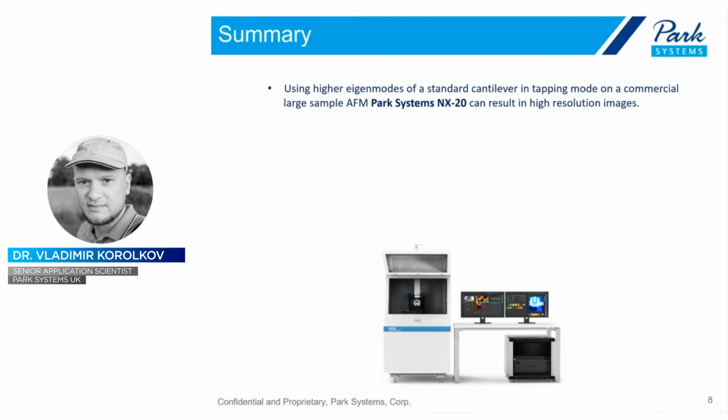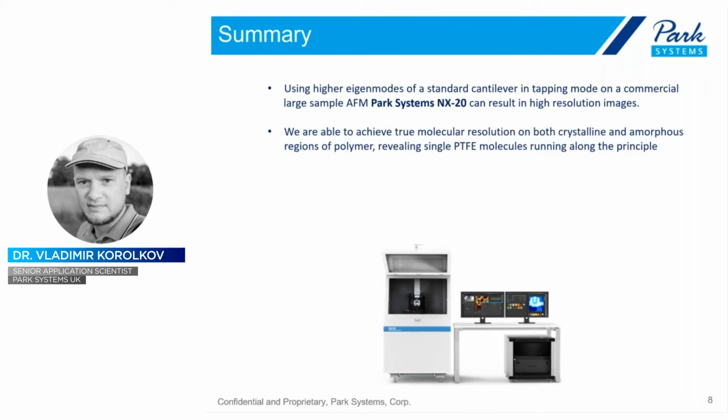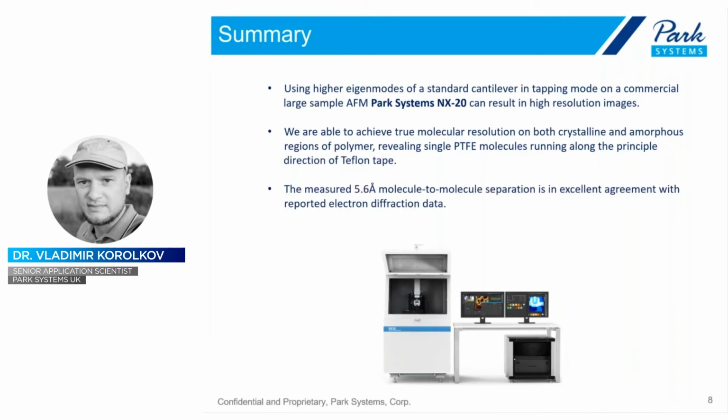single PTFE molecules on a real-world polymer sample on our Park Systems NX20 AFM. We can achieve true molecular resolution, and in fact we can achieve it on both the crystalline part of the polymer on the lamellas and on the amorphous region, because we can see how those molecules that go into the amorphous region, how they form some kind of structure there. And what is critical, the measured